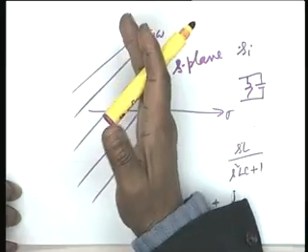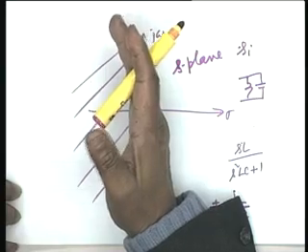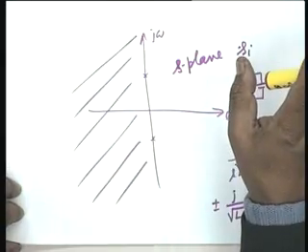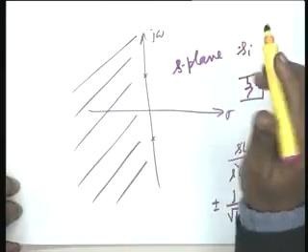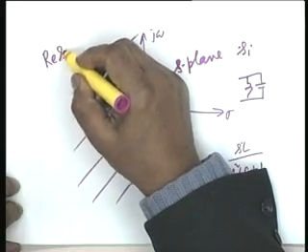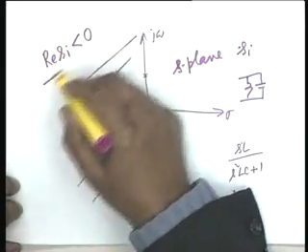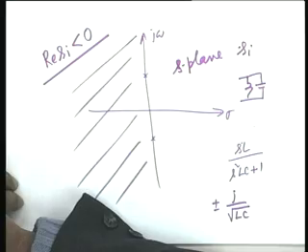If the left half of the plane is to include the j omega axis, we call it a closed left half plane. Closed left half plane, that is, the boundary on this side is closed; the j omega axis is not available to the right half plane. Is that okay? On the other hand, if the real part of s_i was strictly less than 0, then we would say s_i's lie in the open left half plane. Is that clear? Open and closed.